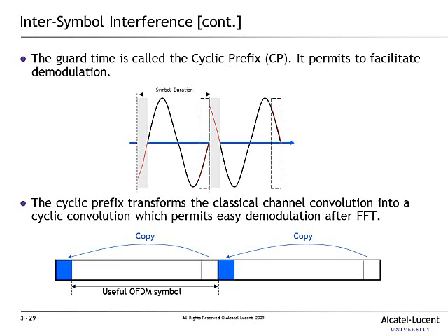Now, somebody did some research on this, did quite a bit of simulations and test runs, and found another way that we can implement the same thing. Instead of transmitting nothing in the guard intervals, what they did was take the last portion of the symbol and copy it into the front of the symbol.